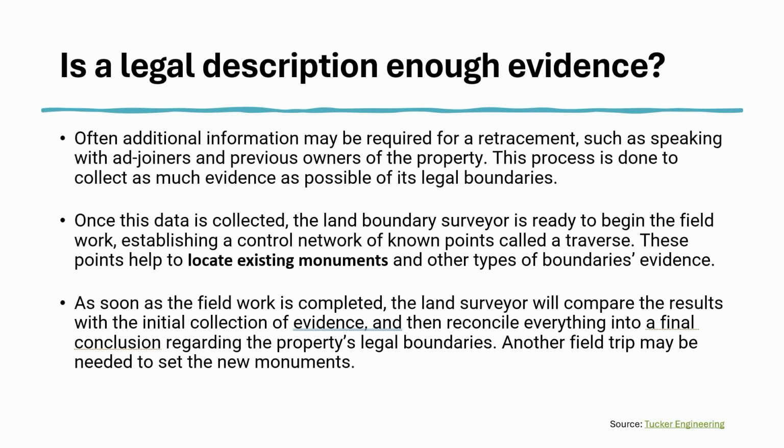And again, the whole point is collecting evidence that's going to help you validate the retracement that you do, whether it's recovered monumentation or, forbid, you end up uncovering a pincushion. Figure out which one of those pins is going to be the one that you should hold to. It's not always which one's the oldest once it turns into a pincushion situation, but if you do find the original, that original monumentation is the most important one. Remember that. And please don't be the surveyor that creates pincushions. It's a headache for everyone.